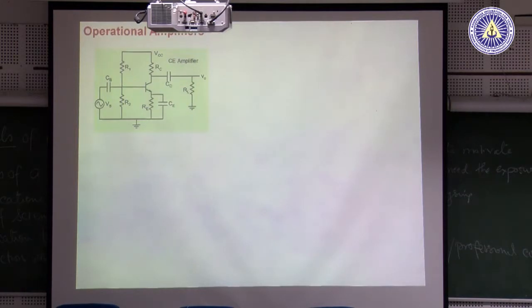The last one that I want to highlight, as I said, each one of these examples you can take to illustrate some larger engineering themes, larger issues, which are important and which maybe students would remember, 1 year, year and a half, whatever down the line. Nitty-gritty details they'll forget. So it's important that we talk about it. Take amplifiers, for example. The details again are not important. Take common emitter amplifier. Even common emitter amplifier is a little bit involved, design of this particular amplifier. You have to select proper bias point, you have to think of stability, you have to achieve certain amount of gain, input resistance, output resistance, bandwidth, all kinds of things that are there. You have to balance all of that in order to design a common emitter amplifier.